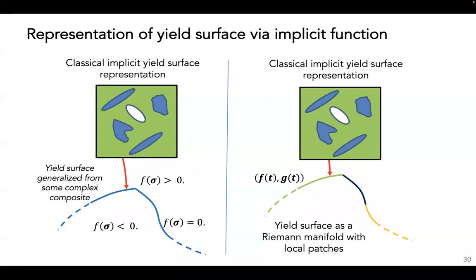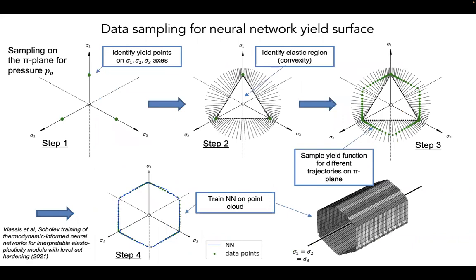I'm kind of recycling the figure a little bit, but here I'm going to reconsider the yield surface. I'm going to do some surgery on the yield surface. I'm going to maintain the principle that F greater than 0 is not possible, F equal to 0 is yielding, and F smaller than 0 is elastic loading. And then I would collect some data. Here I would imagine that we have a physical experiment, and we start with low stress, and to save time, I will start loading at the boundary of the triangle, and then load in all the different radial directions until it yields.